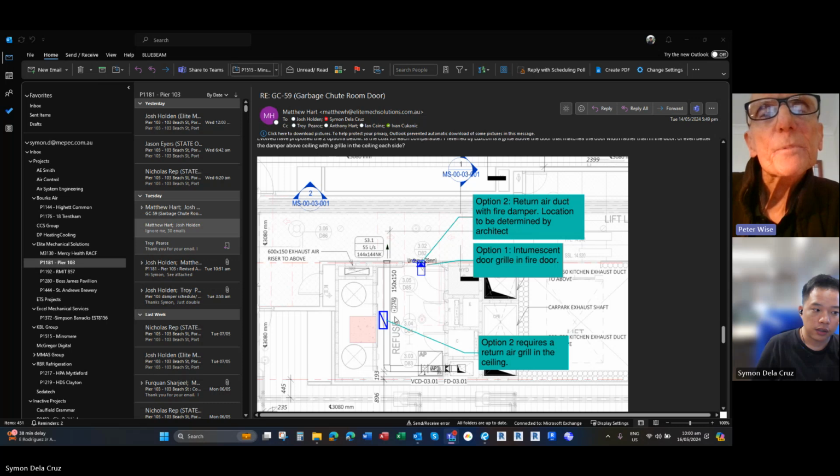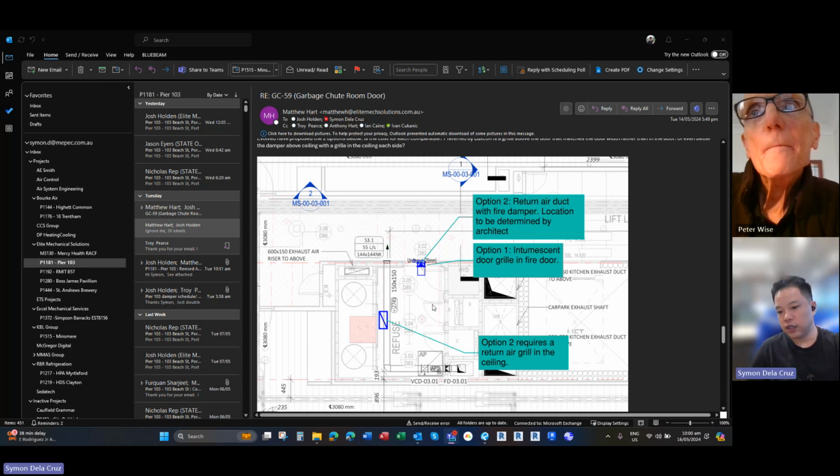Well, how do the fans operate? When do they come on? They operate continuously. This one is operating at 80 and this one at 80. What I did is assume that when you are throwing garbage, you will open only one at a time, not both. So basically I assume it will be 80 liters per second, because if it were 160, it would mean two big dampers and grilles.